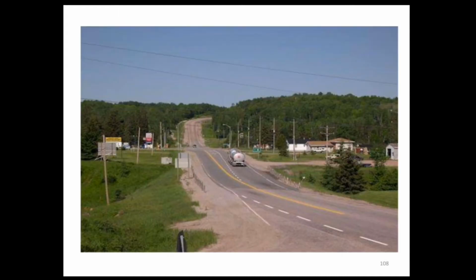As you can see from the figure, there is a change in the vertical alignment. That means there are slopes or grades which influence the speed of the vehicle, and it decelerates at the rise in the gradient, whereas it accelerates at the sloping gradient, and the stopping distances, sight distances, etc.